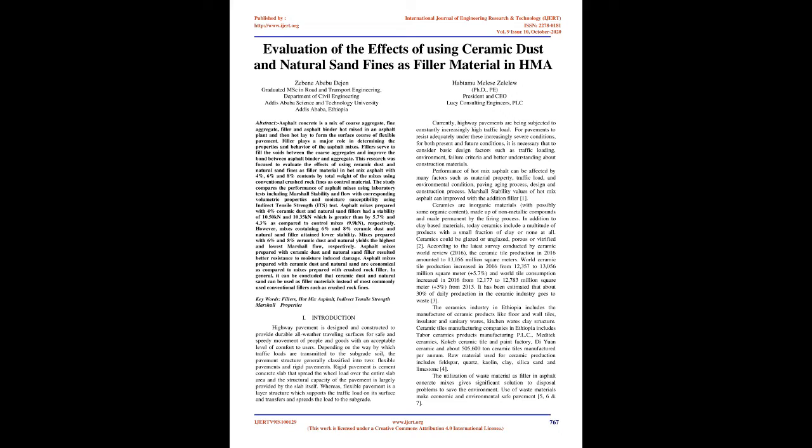Abstract. Asphalt concrete is a mix of coarse aggregate, fine aggregate, filler, and asphalt binder, hot mixed in an asphalt plant and then hot laid to form the surface course of flexible pavement. Filler plays a major role in determining the properties and behavior of the asphalt mixes. Fillers serve to fill the voids between the coarse aggregates and improve the bond between asphalt binder and aggregate.